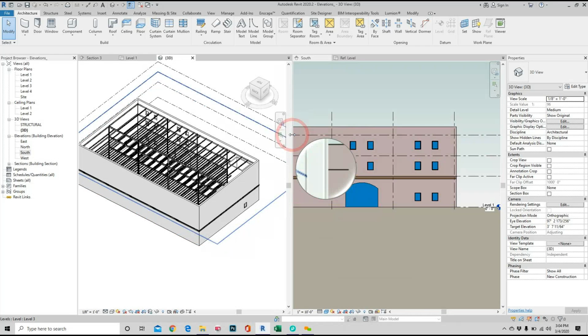Right. What about if you have a pilaster? Anybody has pilasters? At least one of you has to, right? So how do I deal with pilasters? There's two ways. One is I create a family that creates a pilaster. Another way is I create the wall itself. So if I did that, it gets tricky because there's a lot of them, but I will group them. So that way, when you copy the pilaster, it behaves like a family, right? I can keep designing. But let's say I'll do one pilaster that is a family, okay?